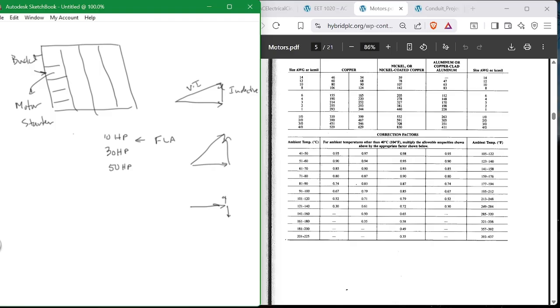Usually one capacitor per motor over a certain horsepower range. Now at Owens Corning it was 7.5 horsepower. Anything above a 7.5 horsepower, we put capacitors on. Now I'm sure today that it's less than 7.5 horsepower. That dates me because that was 40 years ago. Okay. But they still do. You still put capacitors on motors.